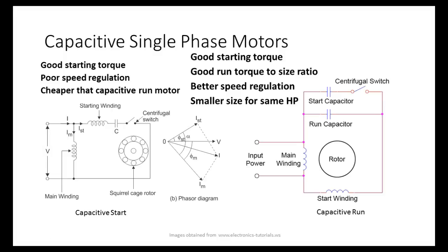So on a single phase motor, if I came out here and swapped L1, swapped these 2 right here, what's the motor going to do? It's going to keep running in the same direction. So what you have to do to change the direction of these things, the DC and the AC motors, is change one of these fields.